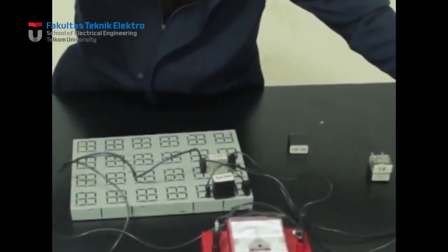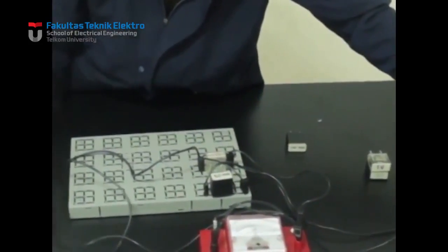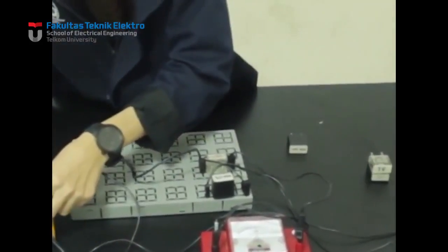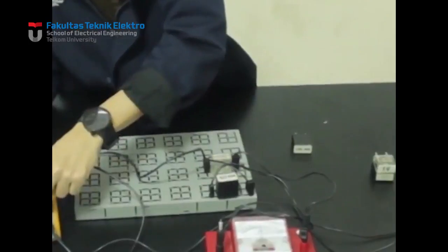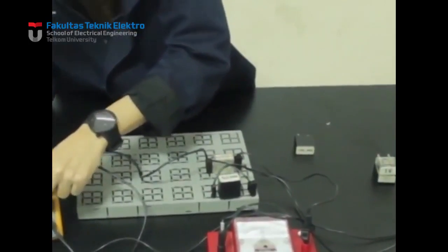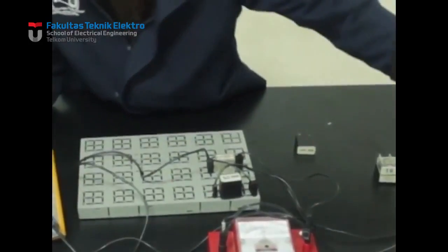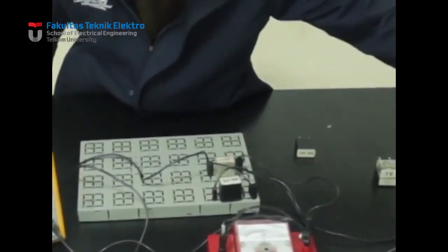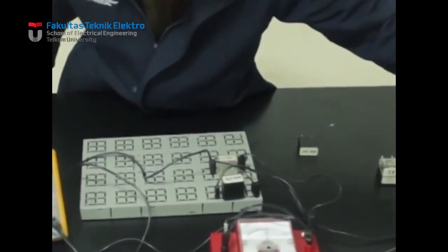For experiments to increase the limit of the ammeter, we need to set the multimeter to ammeter mode for direct current, because we are using a direct current power supply. Because we use a weak current, we use the smallest measurement limit of 2 mA on the multimeter. We turn on the power supply,